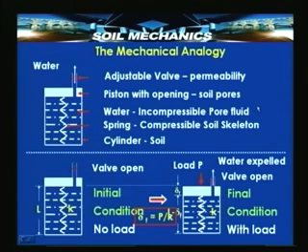Here is a slide where we have a detailed description of a system which is analogous in behavior to the consolidation phenomenon. This is a system which consists of a spring embedded in a cylinder with a piston and containing water or a fluid, so to say.